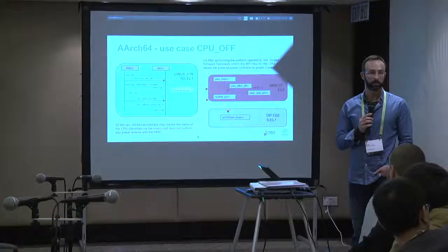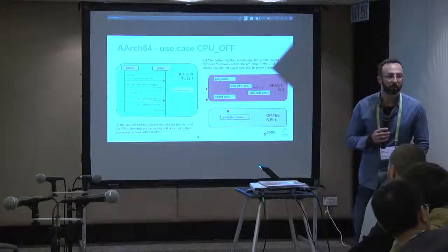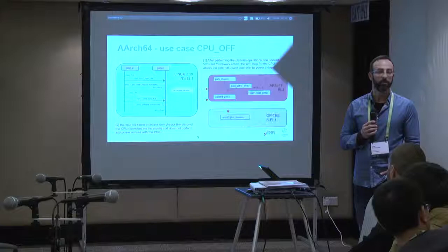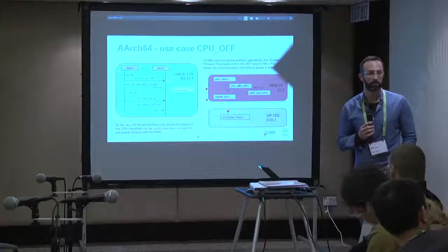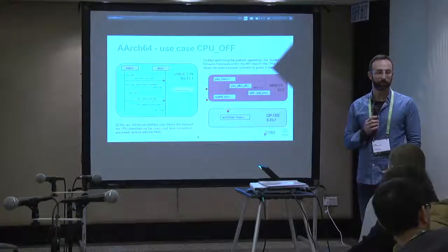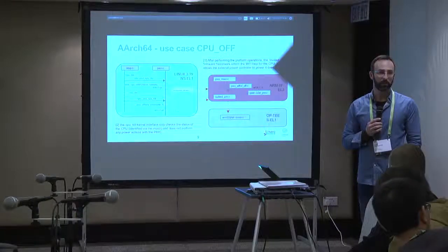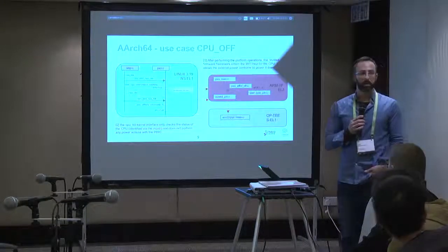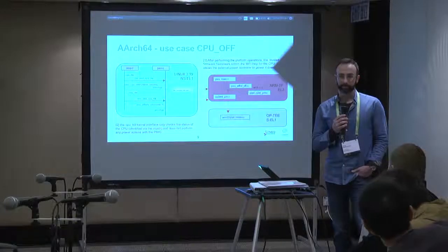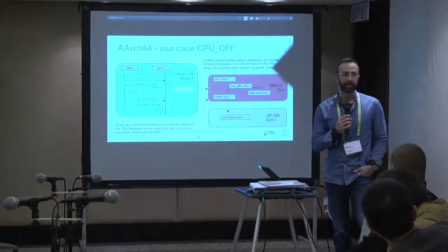That's it. Sorry? I mean, on one side, you have PSCI that will power down the power domain and send some command to the PMIC. And for the voltage scaling and the frequency scaling, it's the CPUfreq driver. So both are accessing the PMIC, maybe the same kind of register. Possibly, but I don't know how that is resolved.